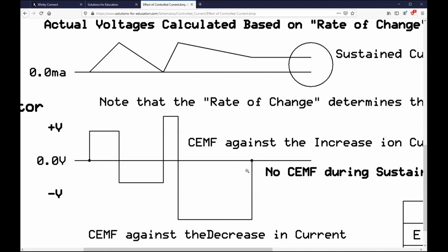Oh yeah, I've seen it happen. Modern capacitors have some scoring on the top, which is a weak point. If they build up pressure, they'll gradually expand and burst through the top. In the class one time, this was beginning to happen. I could see the capacitor swelling, and I reached over and flipped the switch off because the student didn't realize how close he was to having that bomb blow up.